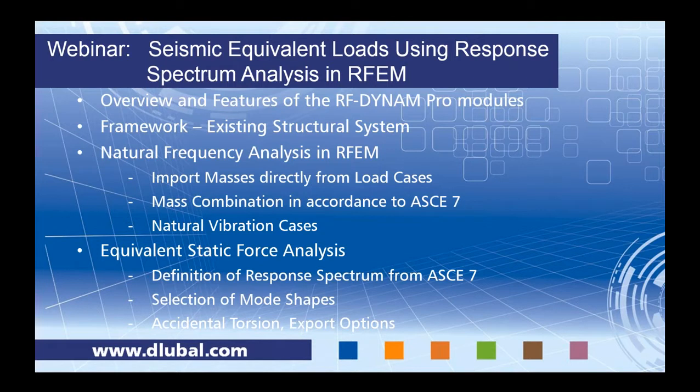We'll be performing a natural frequency analysis today in RFEM. Here we'll be importing masses directly from load cases. We'll create a mass combination in accordance to the ASCE 7, and then we'll be taking a look at the different natural vibration cases. After this natural frequency analysis, we'll go ahead and perform an equivalent static force analysis.